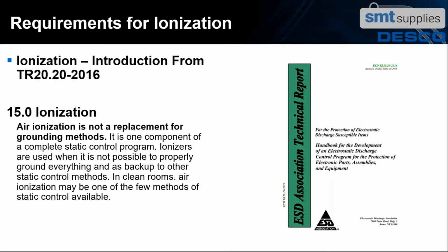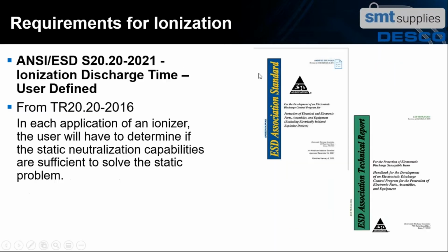And we'll talk a little bit about each of those a little bit later. And again, as we saw before, the discharge time is user defined. So you have to decide how fast the ionizer has to work to do its job. And we're going to talk about that a lot more in the demos.